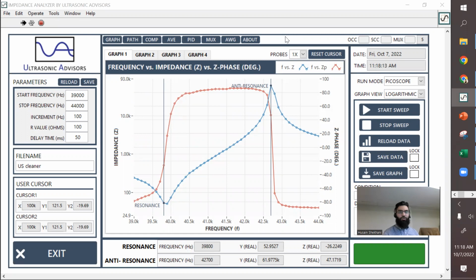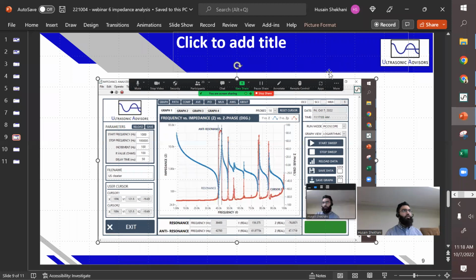So there's two questions here. Are the rest unwanted measurements? We saw many resonant frequencies. Are these unwanted? They're not unwanted, but they're going to exist because this is a real resonator, a continuous system. So there's going to be multiple resonant frequencies. That's just part of what it is. It's not a single dimensional system. It's a continuous mechanical system, so there will be other resonances, but we don't want them close. As long as they're far, they can do their thing. That's basically what we say about the other resonances, but they're insignificant as long as they're not close to the actual resonant frequency.